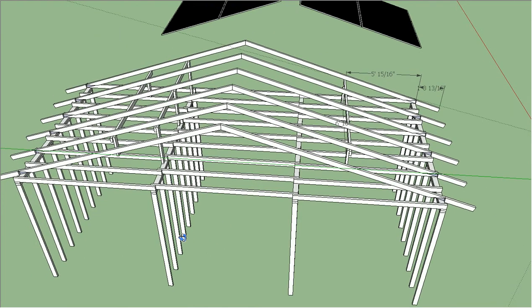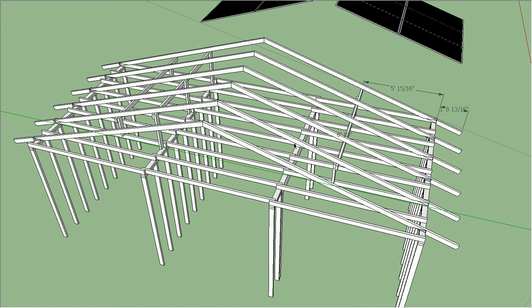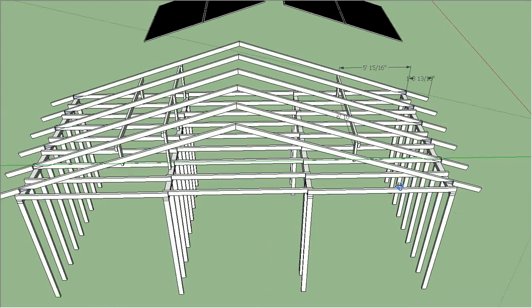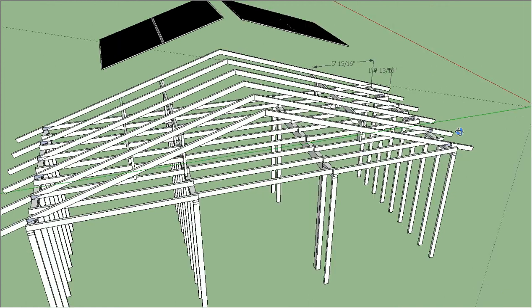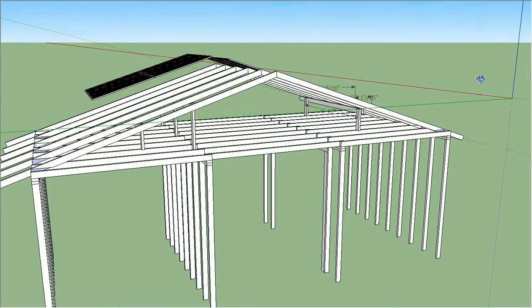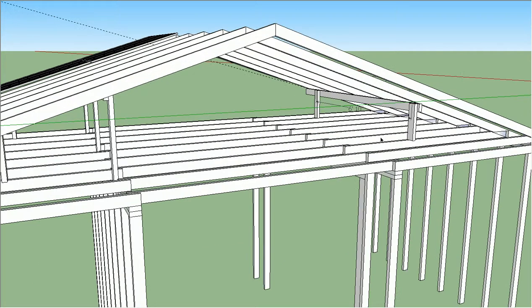And those solar arrays are going to be applying their loads to all of the rafters in the structure, at least those which are mounted to. And those rafters are going to experience both the gravity, the weight of the array, as well as when the wind blows, it's going to sometimes press the panels down and sometimes pull it up. So it's going to have some fluctuating loads in there.